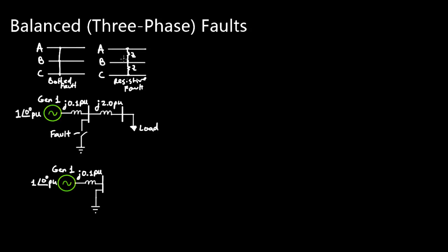Now that may be a couple of things. Usually when it's a three-phase fault, it is the arcing resistance of the arc between conductors. So if you have a transmission line that's spaced out by a couple meters or several feet between each other, if they short out together, all three of them, and they have some resistance, it's probably just an arc between the conductors, meaning it looks like a lightning strike. Basically, the insulation of the air separating the conductors breaks, and you'll see a spark in between the conductors.